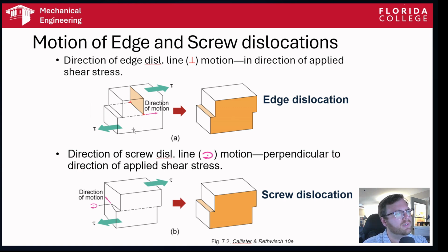And then if we move into screw dislocations, remember we talked about both edge and screw dislocations, and also mixed dislocations, but they're just a combination of edge and screw. The same thing can happen with screw dislocations. We apply a shear stress in a similar way, but instead of moving the entire two halves of the surface along one another, this actually unzips.